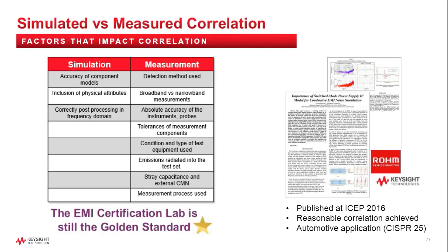Will using faster edges not increase the signal spectrum? That is, will we have higher frequency noise? Most general answer would be it depends. Most probably yes, but you can experiment with the different edges. You can do the extraction of the board with an assumption of higher edge speeds, so that the information will be there for you to experiment with, and then in the setup of the simulation, you can change your edge speeds and see the effects.